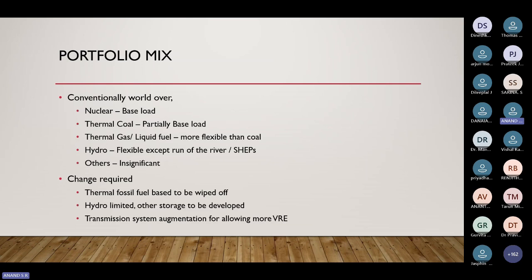So if you have a generating station very near to inhabited areas where heating requirement is also there, part of the steam can be diverted for that, and actual generation can be reduced, because the controllability of the generation depends on controllability of steam. If you have to maintain some steam because of boiler constraints, then if you can divert some steam, it is possible to control the generation much more.